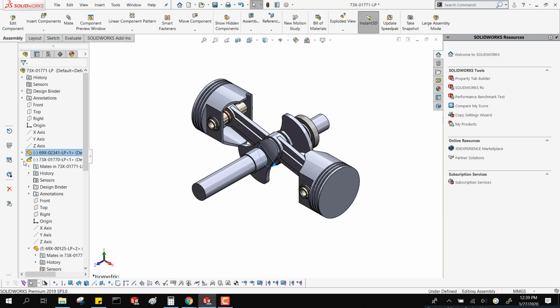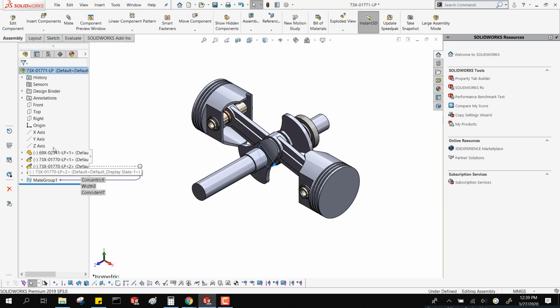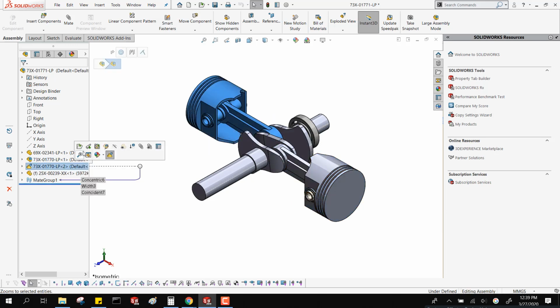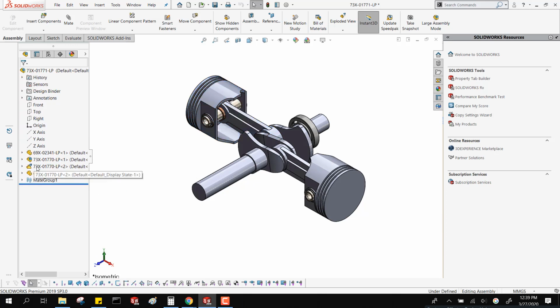You'll see that both of my assemblies here don't look like the usual assembly icon. My usual assembly icon, which is at the top of the tree, looks like a part icon with a little blue block sitting on its shoulder. But these look like a part icon with a little blue block floating over its shoulder. That means that subassembly is set to flexible. I can click on it, and you'll see that it changes back. It also changed the orientation. The orientation that it uses, if it's not set to flexible, is whatever orientation it was last saved in at the subassembly level.